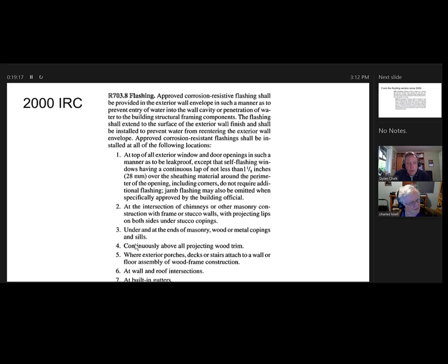You mean like the corbels, like the entry porch posts and stuff, that extend by a barge rafter, for example. Yeah, knee braces, and they always rot out. At least the newer ones; the older ones seem to hold up really well. So they should be flashed, and on really high end jobs they will be. But you don't see it in basic production construction often.